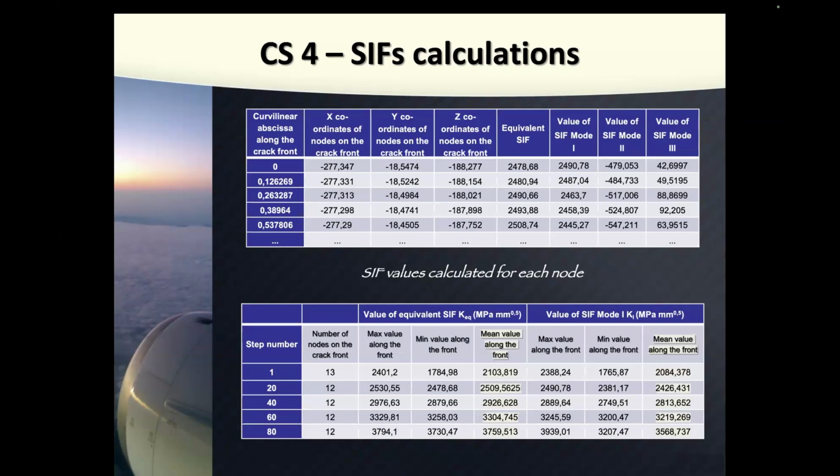So this is why we divide by a factor of 3. If I get 100,000 cycles, I would say replace this after 30,000. Do not wait for 90, because you never know. Don't forget that, fundamentally, fatigue is a statistical problem. A crack will occur, sooner or later. It's a must. So better to do some preventive things sooner than later. Okay, thank you for your attention.